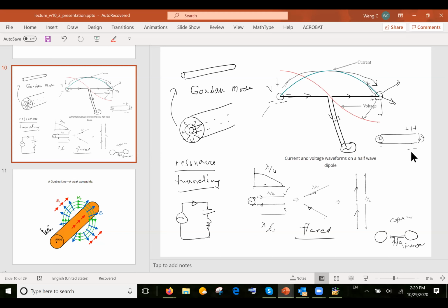I was wondering about that dipole with the two spheres at the ends, mostly. Oh, there would be a capacitance here too, because if you think about this, if this is positively charged and this is negatively charged, there'll be a fringing field. And this capacitance is bigger. And Hertz deliberately made it that way so that he would get a bigger capacitance.